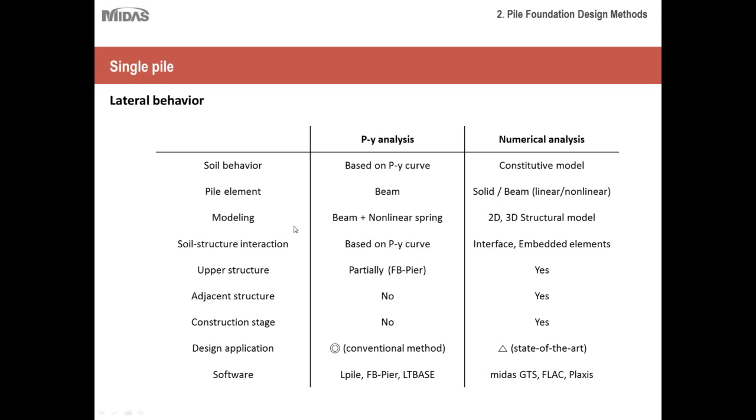Then when you are creating the model under PY analysis, you are dealing with a set of beams and nonlinear springs, whereas under numerical analysis you are actually dealing with a 2D or 3D environment of a structural model, where you'll have the real soil strata represented by a constitutive material model, the pile member represented by a 2D or 3D member with linear or non-linear material properties.